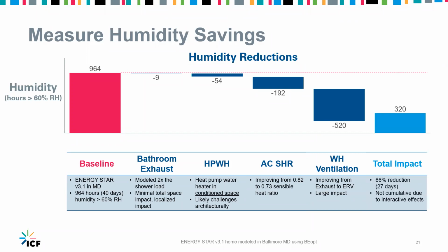So put them all together, we got down to 320 hours. That's cutting it to about a third of what we started. It's about 27 days' worth. So that's a big change, and definitely most of it was from the ventilation strategy that was used in that home.